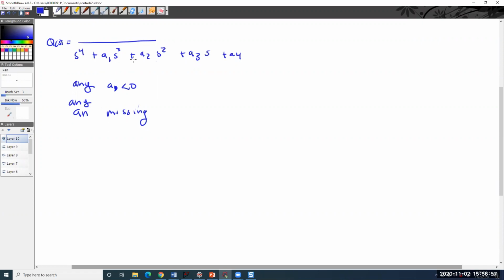Okay. So let's say this is missing. Let's say this was our original numerator, right? Well, then we have G of S times B. Well, it's the constant term that's missing. So all it has to do is be K times B. K just has to be greater than 0, and we'll have a term here, right?